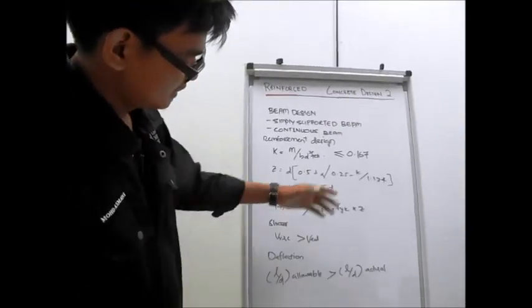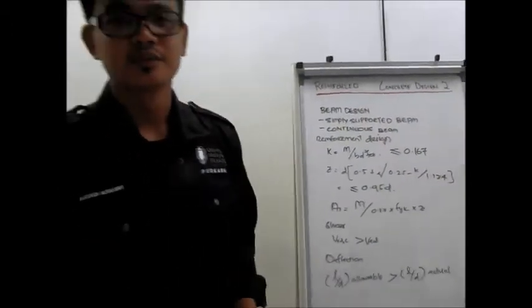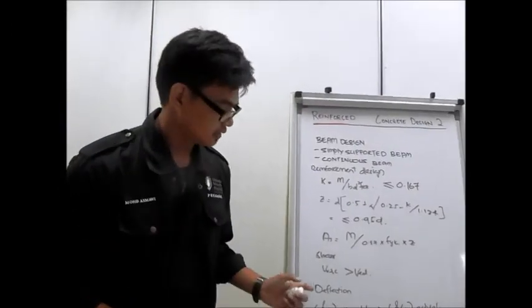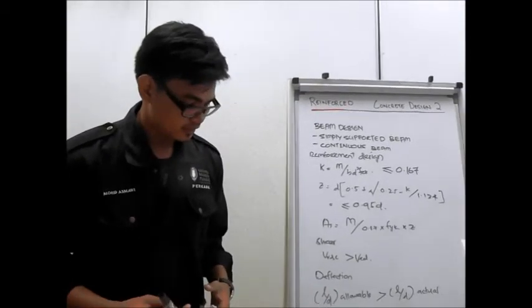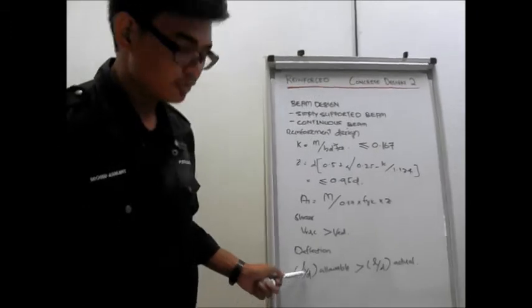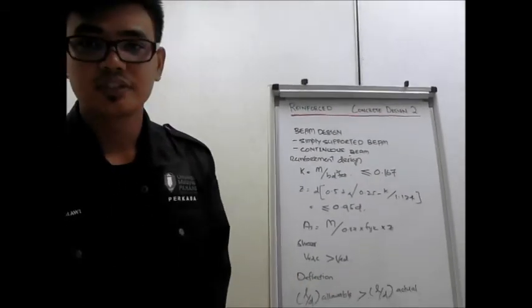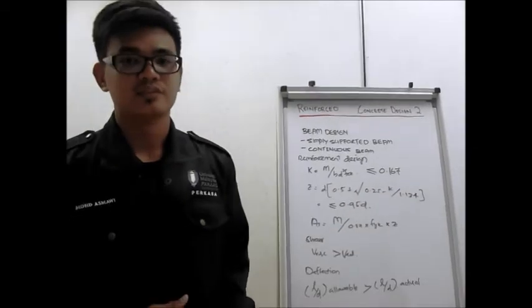Okay, after we finish the shear stage, we need to proceed to the deflection step. For the deflection step, we need to calculate L over D allowable, which must be bigger than L over D actual.